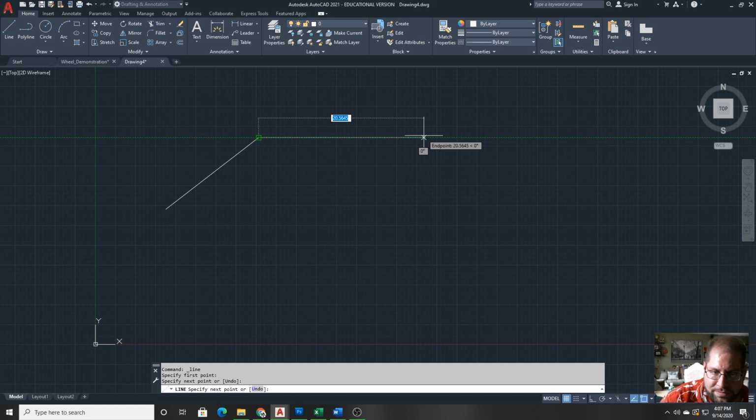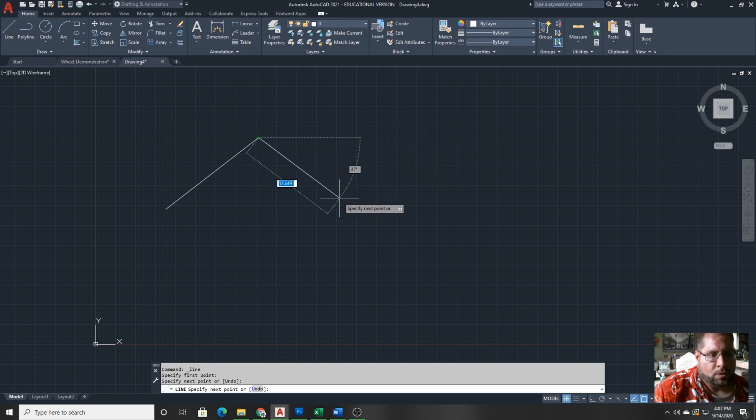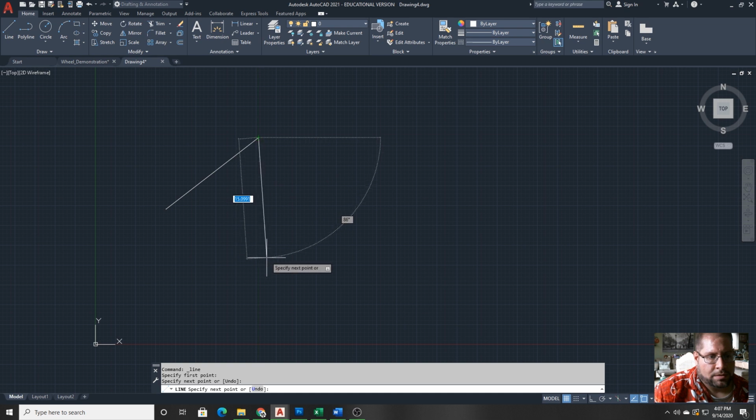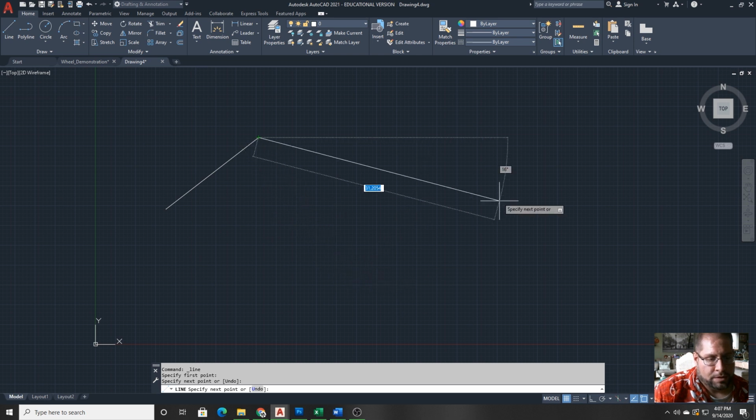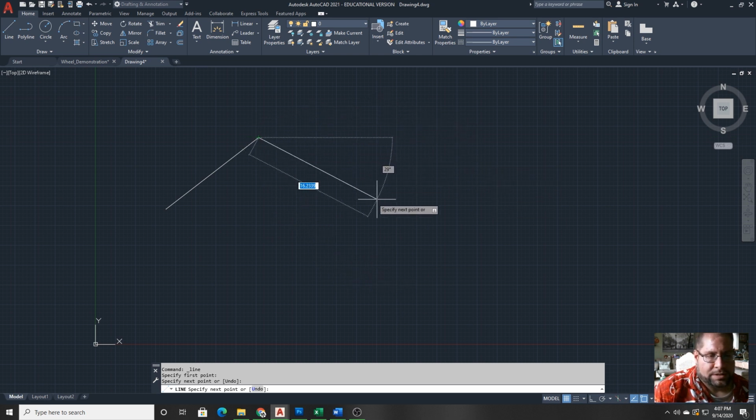The word snap is not a word that I'm coming up with. Snapping is actually something that's built into AutoCAD, and you can see that anything that is snap related does appear green on the screen by default. I could also try to snap it vertically downward, and as I cross that vertically downward point, I can always just lock onto it by moving the mouse in that particular direction. Let me click down a second point.